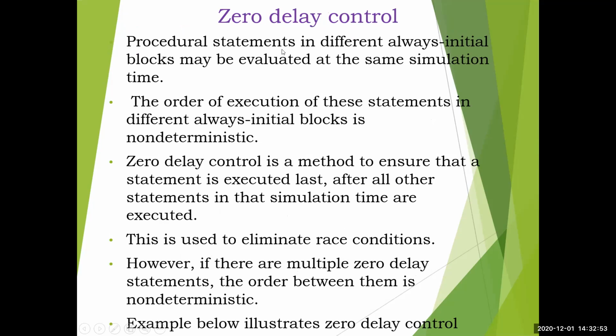Procedural statements in different always or initial blocks may be evaluated at the same simulation time. Okay, so as we have mentioned, if you write multiple initial or multiple always blocks, all will start the evaluation at the same time, but the completion may take different times, that we have mentioned. The order of execution of these statements in different always or initial blocks is non-deterministic.